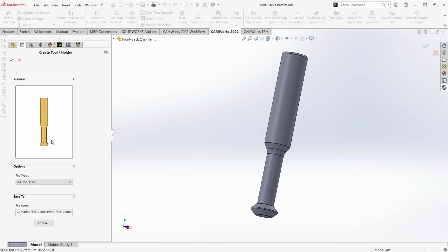The reason this is possible is because I took that translated DXF file, that sketch geometry, moved it to the origin of the sketch, and rotated it 90 degrees so that it is oriented this way. So you have the y-axis as your rotary axis, and the sketch oriented in the positive x and y plane. That's actually important for the sketch. It needs to be centered on the origin, and it needs to be in the positive x and the positive y direction. Once you've got that and you do a revolve solid, you can turn it into this shape definition here.